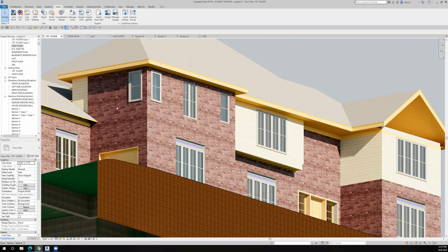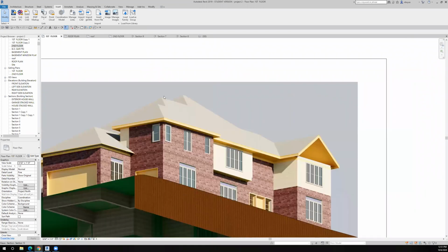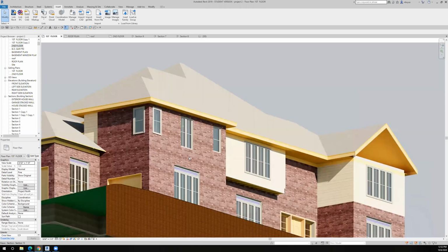Generally, that soffit will have some sort of air screen on it, which allows more air to get inside of the roof space. We also would put vents, ridge vents across the top here, or some sort of vents that allow the air to escape. And what that does is, if you don't ventilate your attic space, the moisture builds up, and over time it will deteriorate the structural members in your house. So you definitely want to have ventilation there, but we don't have to show that for this class.